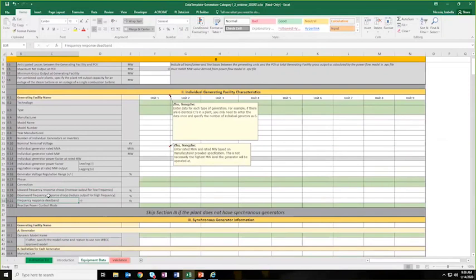Yeah. Okay. And then, taking a look at the power factor, the leading and lagging power factor range, that is just from the generator data sheet without the OEL and UEL. Yeah, this can be just from the sheet. Then we will use this as one of the reference data when we evaluate your overall power plant reactive capability. We also ask for the Mod 25 test report. We rely more on that test report than this data. This is like the outer bound of your capability.